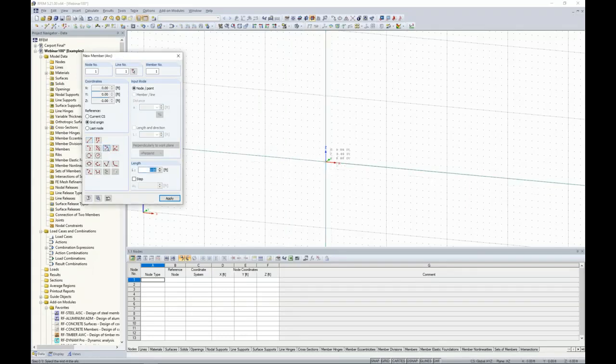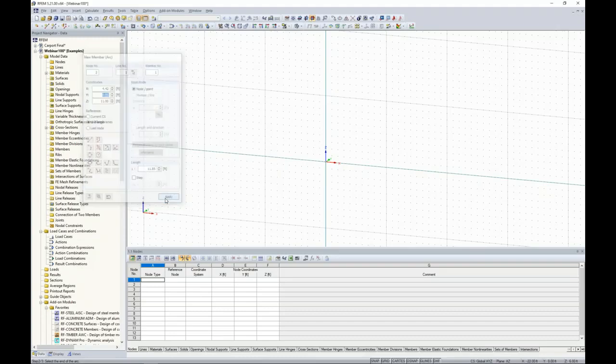So I snap to the origin at 0, 0, 0, and then my second point can either be defined on my work plane here, but in my particular case, I don't have exactly 1 foot increments for my second point, which is what the default is for my drawing grid. So what I can do is just type in the coordinate points directly at 4.42, 0, and 11. Now you want to make sure not to drag your mouse outside this dialog box because as you'll see, everything resets to the current position of my mouse on the work plane. So we'll retype that in at 4.42, 0, and 11. We scroll down here to apply.